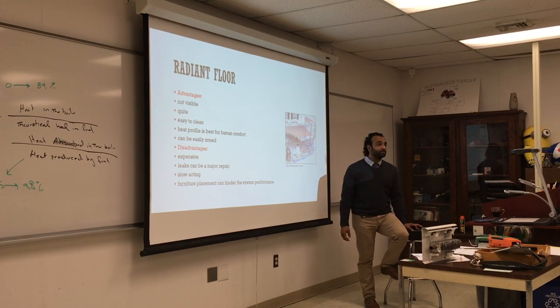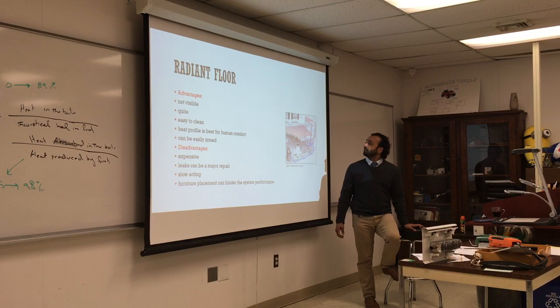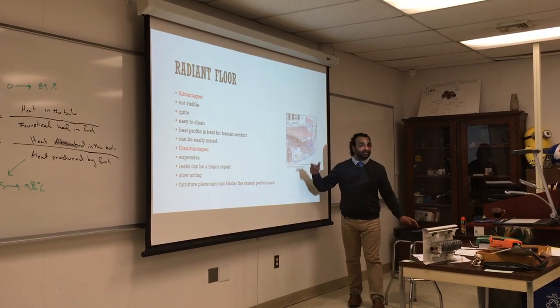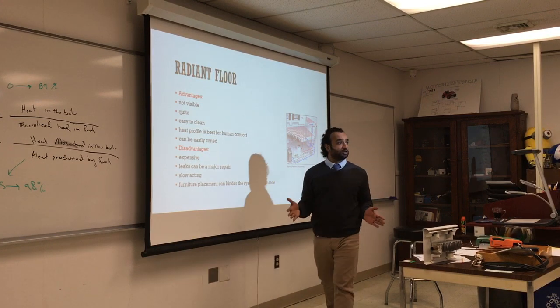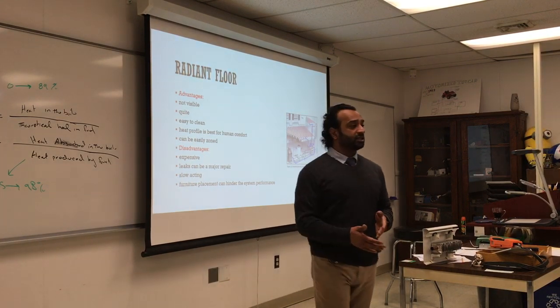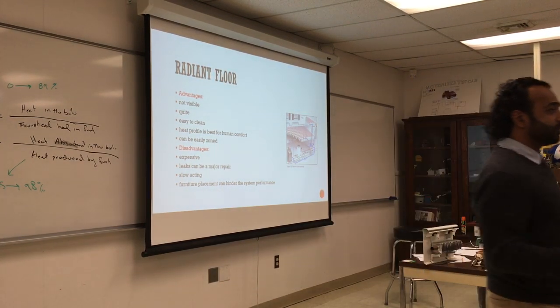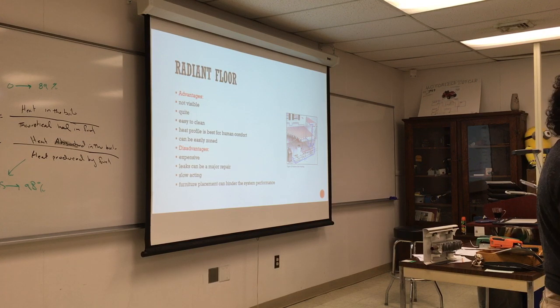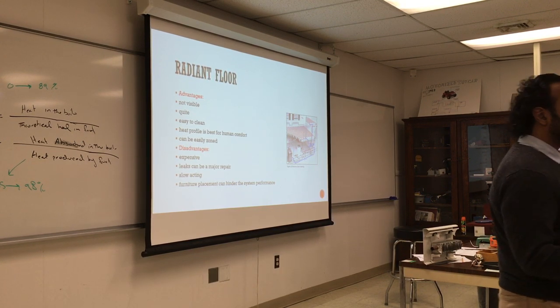They charge you a lot because it involves a lot of techniques in the installation. The spacing between those pipes dictates how much heat you get. The water temperature does not exceed 90. It's between 80 and 90, which is not that much. So instead of heating water to 180, we're heating only to 85 or 90. And that'll be enough to heat your entire house.